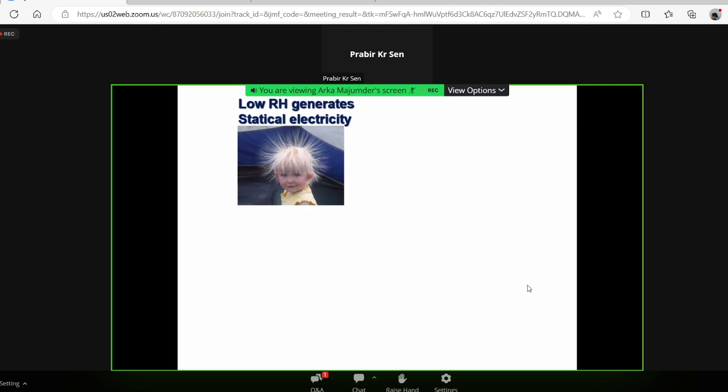And when the RH is high, say 80% RH inside an electrical room, that may at times create condensation of water on the cold surfaces. And that condensed water may again cause short circuit between two closely spaced conductors or electrical elements of an IC or a PCB.